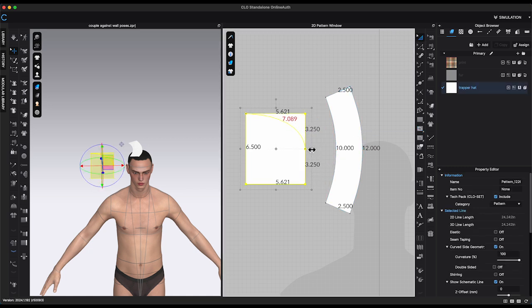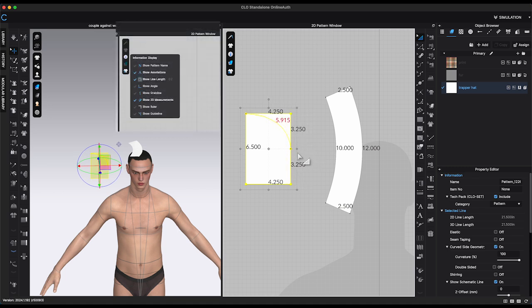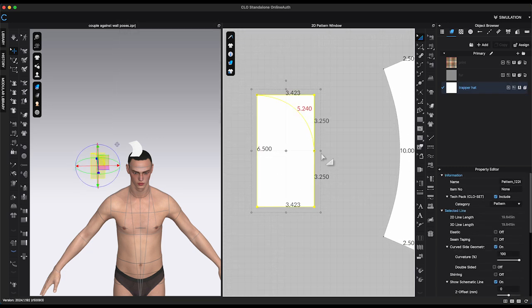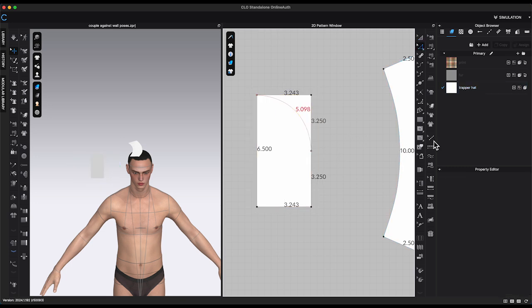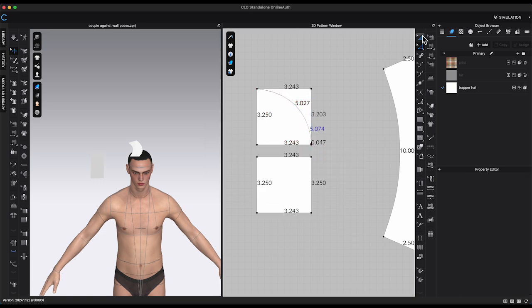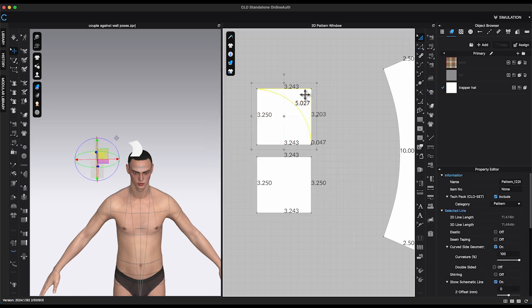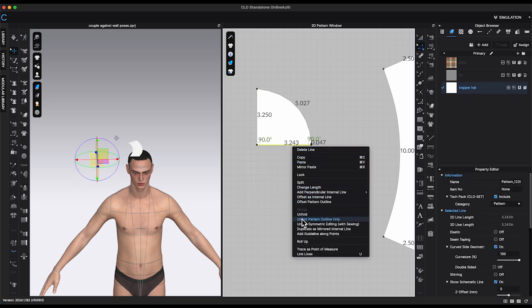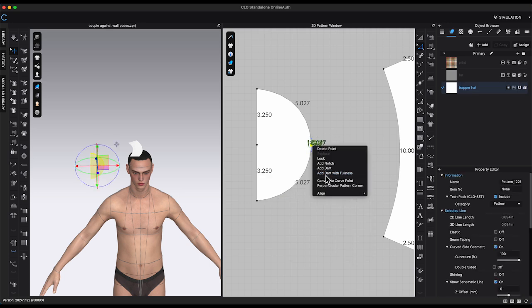I need to scale down the square using Transform Pattern tool. Turn on Show Line Length from 2D window toggle menu to make it easier when adjusting the length. Once it's close enough to 5 inches, add a center internal line. Right-click and choose Cut. Select Curve Segment. Right-click and choose Cut. Delete extra pieces. Then unfold to get a symmetrical pattern.